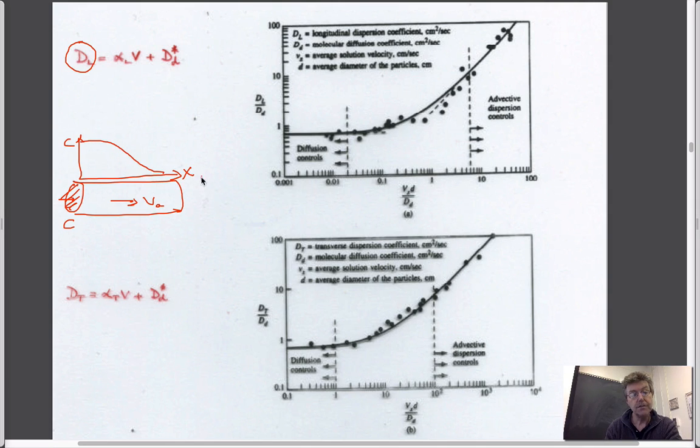But what is much easier to do is look at the concentration at the arrival as a function of time. So this represents a snapshot at time t. If we wait for the stuff to come out of the end, we'd end up with a residence time distribution which looks like this, right? This plug flow would be for dispersion equals 0.